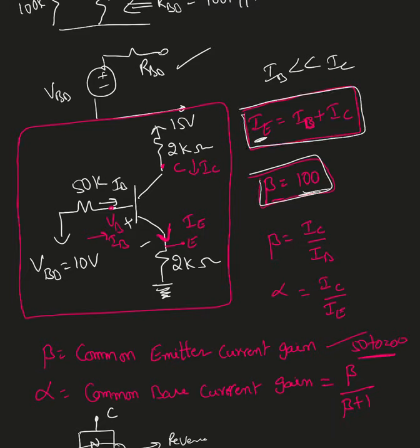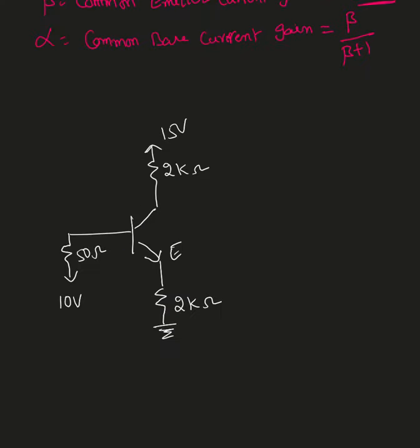It's just like the voltage at VB always controls the current passing through the emitter and the collector. That's what the transistor does. Okay. To avoid confusion, I redraw the circuit here. So now I'm taking this as an active mode of operation. We'll take this as 0.7 volt, since the base to emitter junction is forward biased.